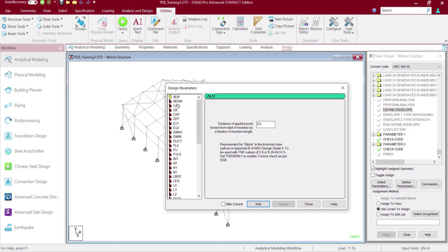Now web tapered section, if you might have seen some industrial structure having the tapered section. These are huge sections. Sometimes the depth is as great as 600 to 750 mm. Now, these are the sections whose web generally gets tapered off, and these are not hot rolled because you are slicing out those tapered shapes, and welding the web and the flange by the method of welding.